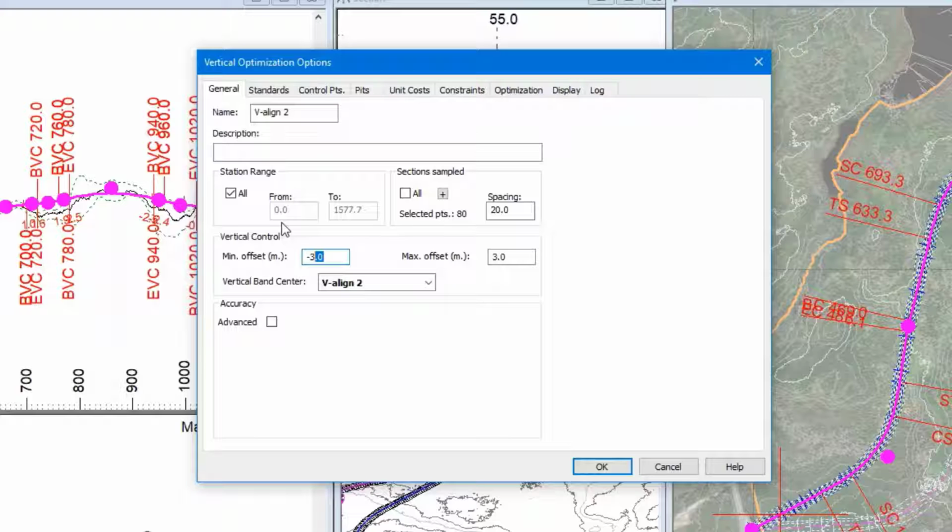The wider the band, the more granularity you have in your sampling. So narrow band, you get really not much interpolation between the samples. But at some point, you're not gaining much by having a tight band and you're constraining where things can be.